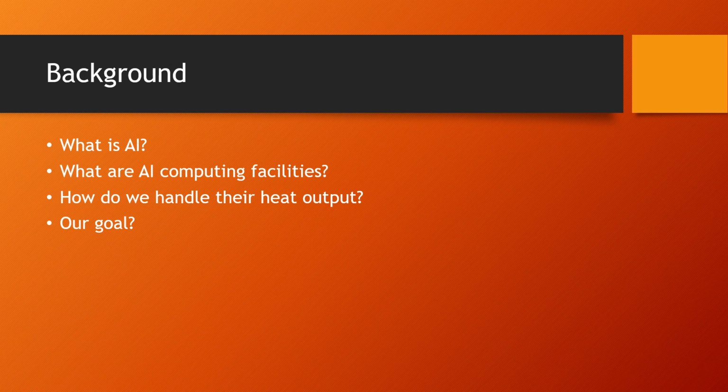There are many ways to combat this, between raising the floor levels as well as the floor arrangements for improved airflow. You can also change the cooling mechanisms along the heat producing parts of the computer, including air versus liquid cooling. But for our goal in this project, we decided to evaluate what the optimal chip layout would be for our design in liquid cooling, deciding between pin fins and straight fins, as well as comparing the use of two types of dielectric fluid for both.